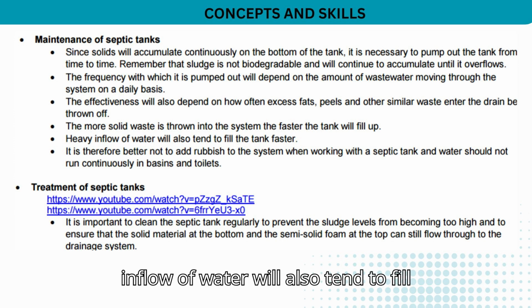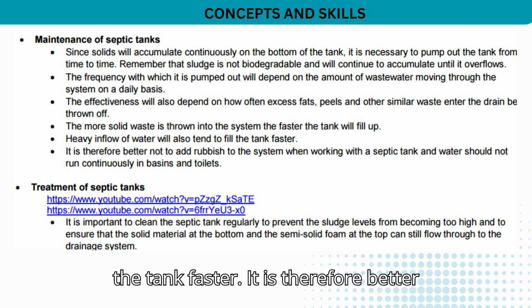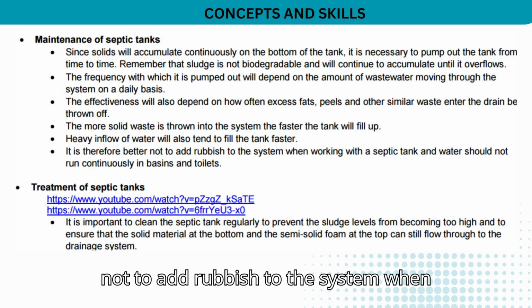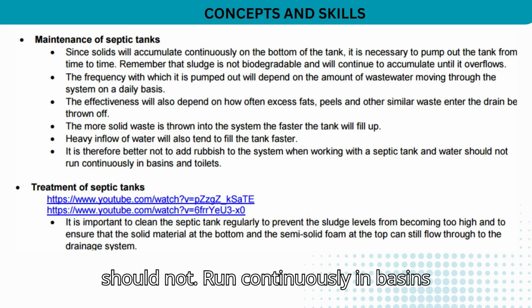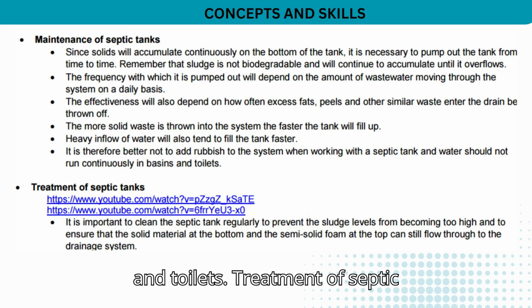Heavy inflow of water will also tend to fill the tank faster. It is therefore better not to add rubbish to the system when working with a septic tank, and water should not run continuously in basins and toilets. Treatment of septic tanks.